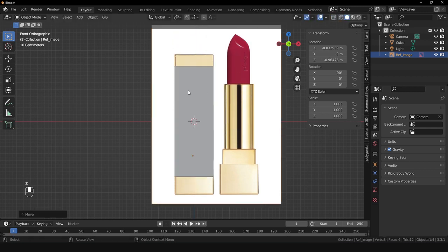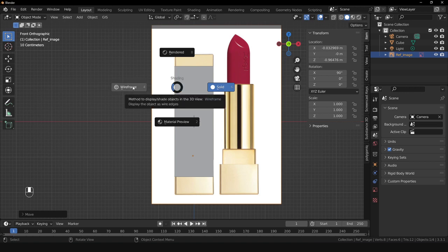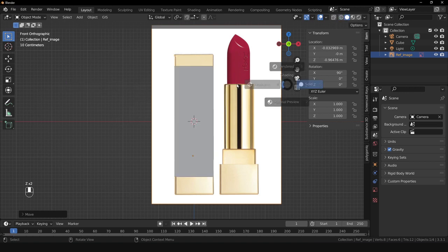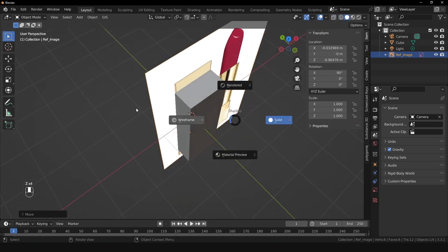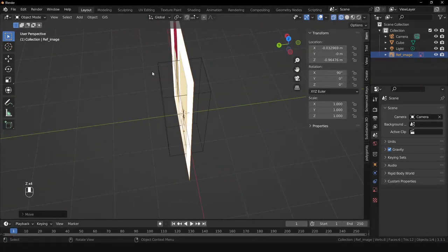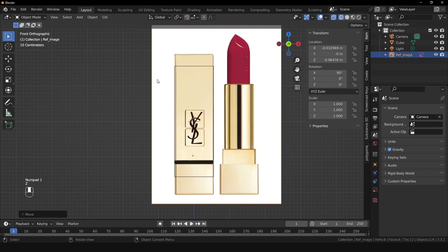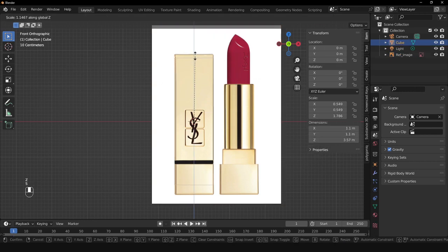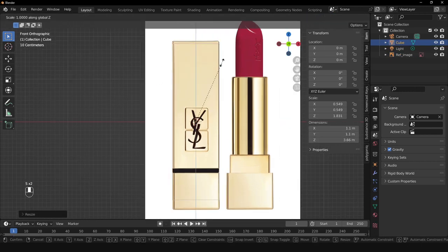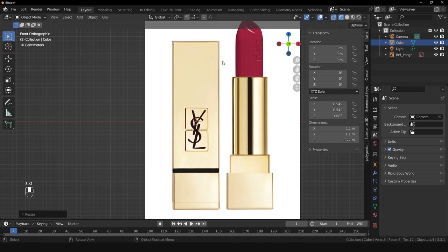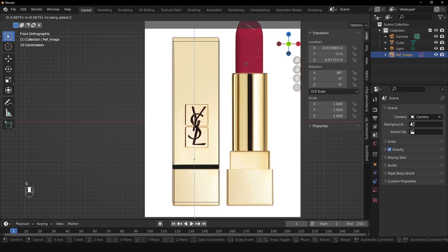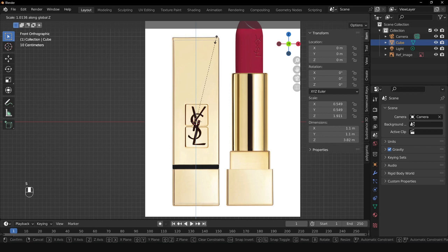Now, I also switch a lot between the wireframe mode and the solid mode. You can do this by holding Z and clicking 4, or just dragging your mouse here and then releasing Z. So with wireframe mode, you essentially look through your model and just see the edges, right? So here we can easily see if we are reaching this height. So scale Z to just scale around the Z-axis, and then I move everything a bit in place.